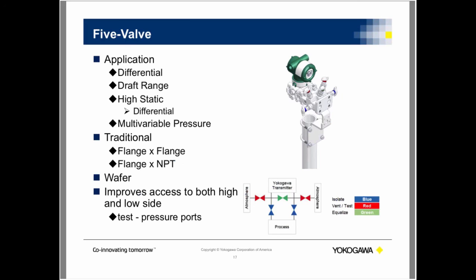It allows you to not create any unnecessary leak paths, and you can also separate it out. Now, you can use the 5-valve to do instrument isolation and zeroing, venting to closed system, and instrument calibration, and it's also used in liquid and vapor services. Again, it ensures a proper zero for your transmitter, allowing pressure to be equalized to prevent exposing low differential transmitters to potential damage.